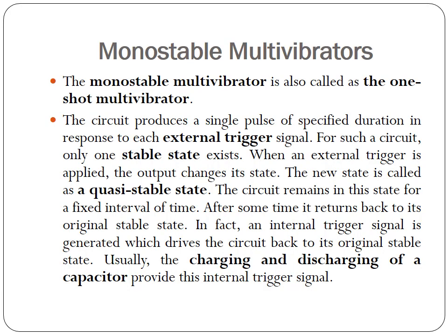Now I am going to talk about monostable multivibrator using op-amp. In this multivibrator, one state is permanent stable state while the other state is temporary state. The permanent stable state is high. Apply a triggering pulse to change output state to low. But this state is a temporary state, so it will remain in low state for some time, and after some time, without applying any triggering pulse, output goes back to permanent stable state, that is high stable state.